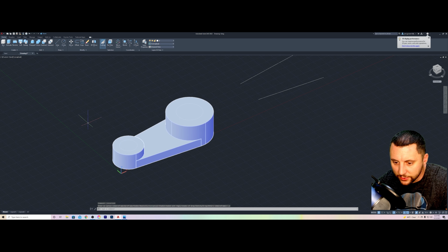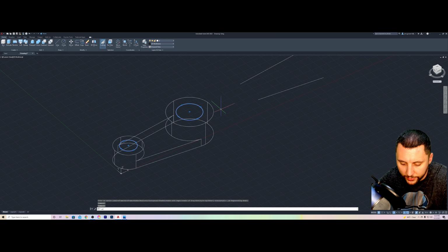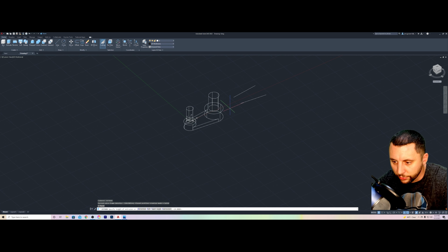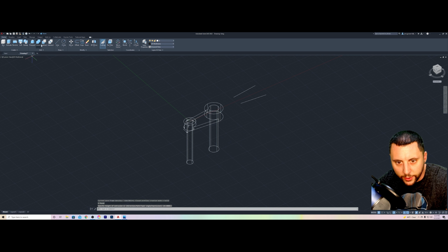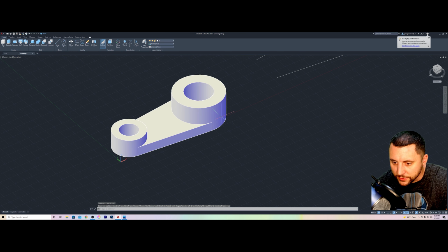I'm now going to take the other circles and extrude those through. You could say, okay, let's do this one -24, and that one -36, but it actually doesn't matter how far you go through, as long as you go through the entire thing. So subtract, main model, enter, and you can do both of these at the same time. Enter or spacebar, I hit spacebar sometimes. Spacebar and enter do the same thing. And we get this, okay?